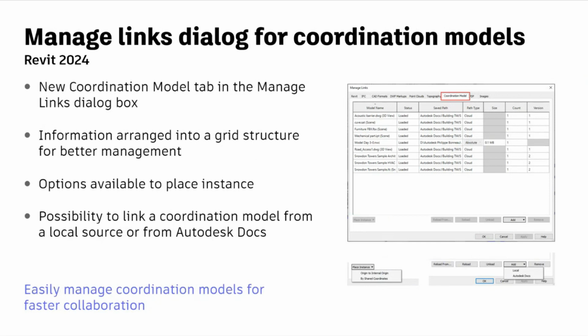We also have a new coordination model tab in your manage links dialog box. The information is arranged into a grid structure to provide easier understanding of the linked coordination models. You can also modify the placement of the coordination model with a place instance object.